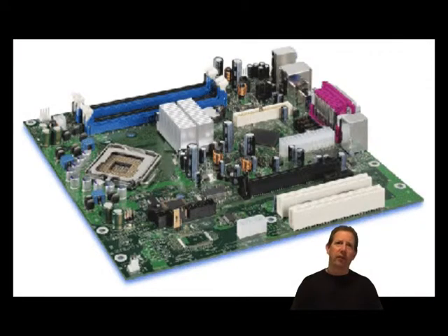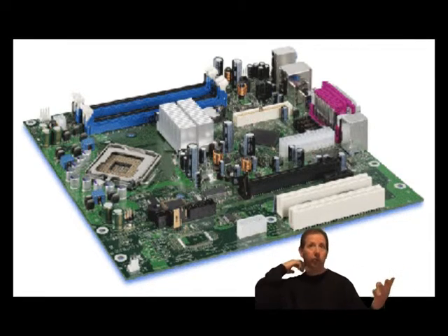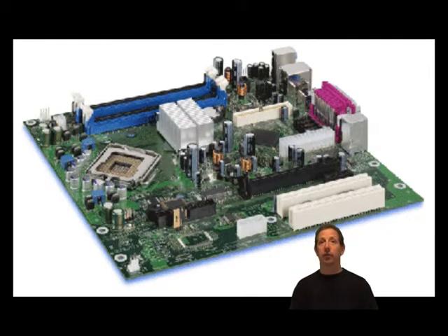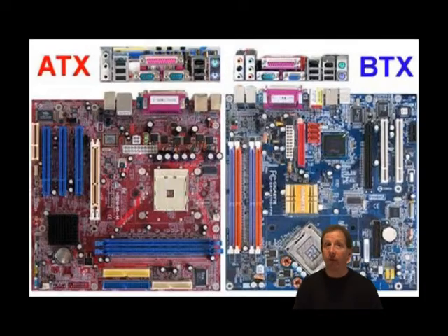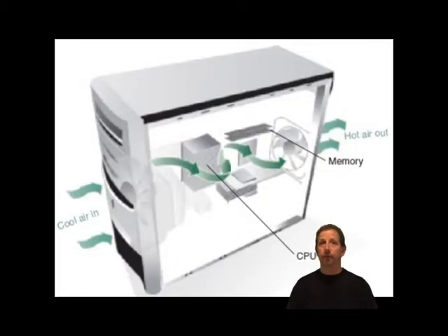Next form factor I want to discuss is the BTX or Balanced Technology Extended form factor, designed by Intel in 2003 for flexibility, and it can be used by everything from large tower systems to those ultra-small systems that sit under a monitor. It was designed to take full advantage of serial ATA, USB 2.0, and PCI Express technologies. The form factor design focuses on reducing heat with better airflow and improved fans and coolers. It also gives better structural support for the motherboard than did the ATX.